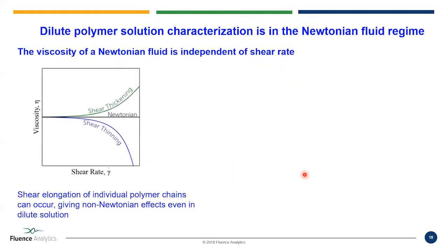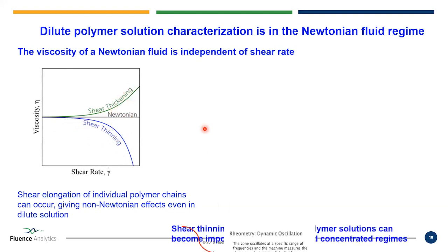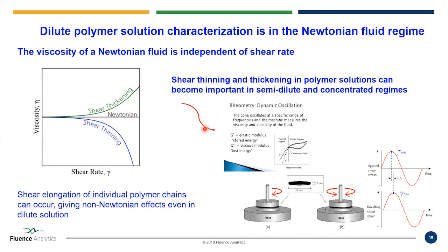So, a quick mention. That's normally when we have what we call Newtonian flow. A Newtonian liquid is one whose viscosity, this eta we're talking about, is independent of how big the shear rate is. Water is like that. But a lot of polymers, as you increase the shear rate, for example by pumping through a capillary more quickly at a higher flow rate, will actually start thinning out. Their viscosity will go down. And some materials will actually go the other way and have shear thickening. So that brings us into what we were talking about before, more like the overlap concentration, melts and liquid states,